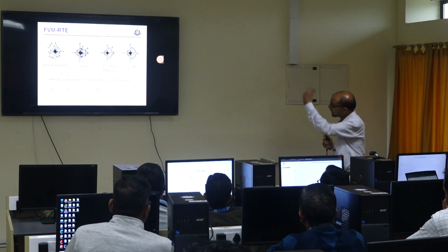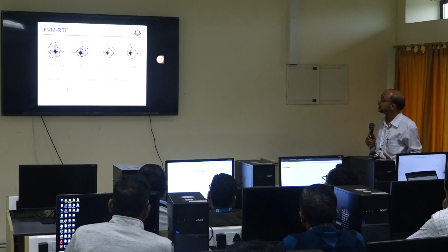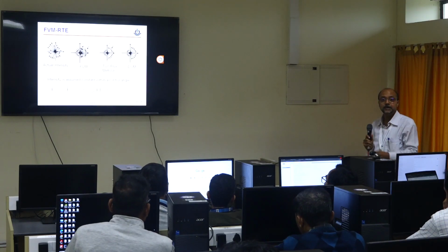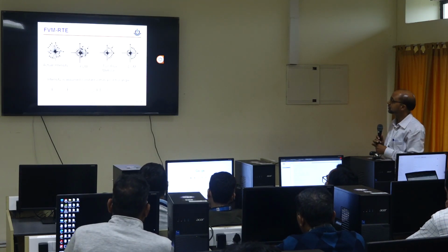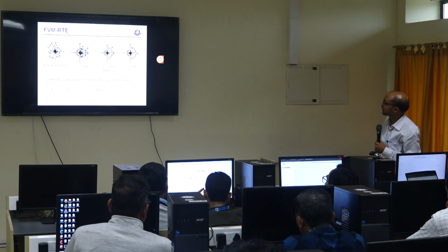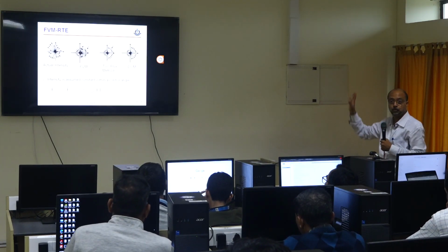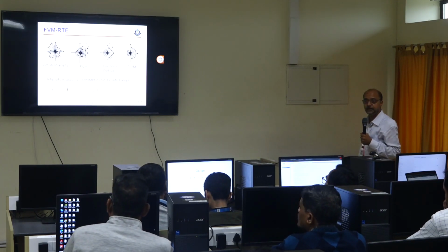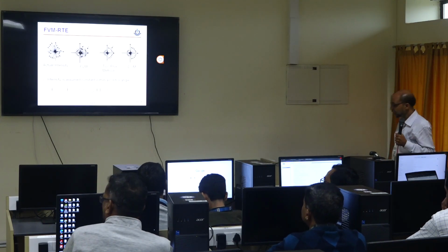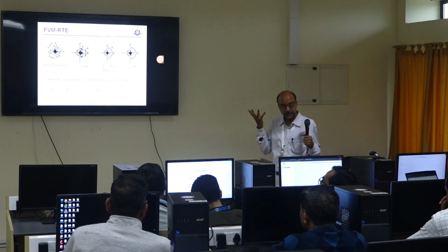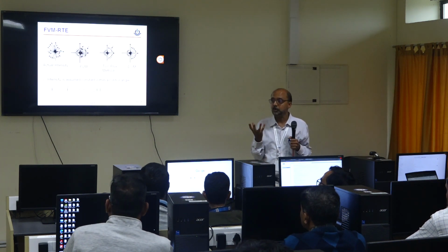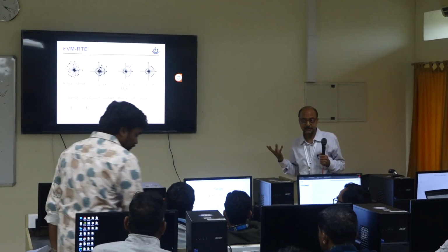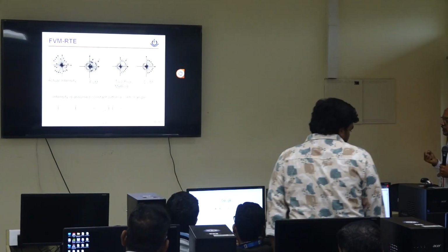So you can resemble the actual intensity distribution quite easily using finite control angle generation. Here I have shown one of the figures. The number of control angles here is 1, 2, 3, 4. Four control angles have been shown here. In each control angle we have a different intensity distribution. So if you are expecting a large variation in intensity in different directions based on your boundary conditions, then you can create more control angles. That is the flexibility you do have.